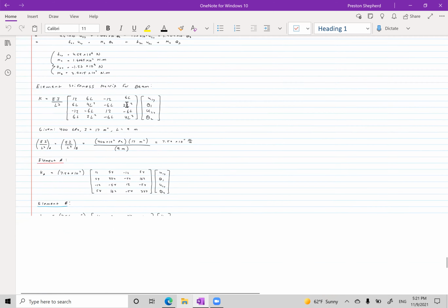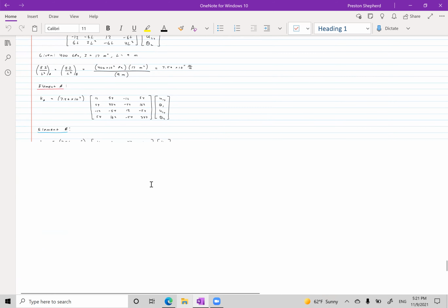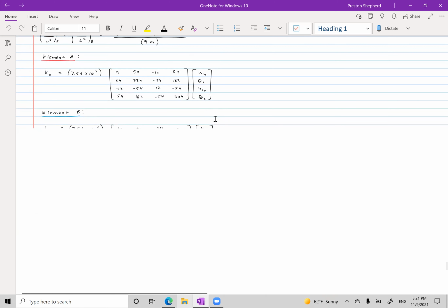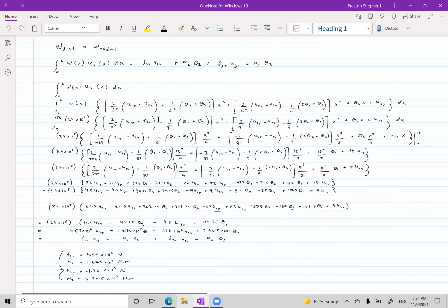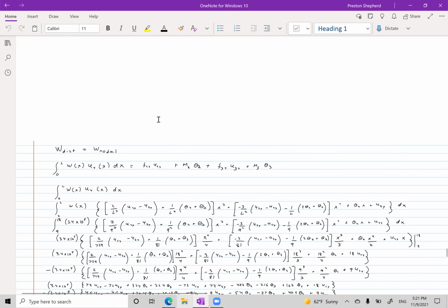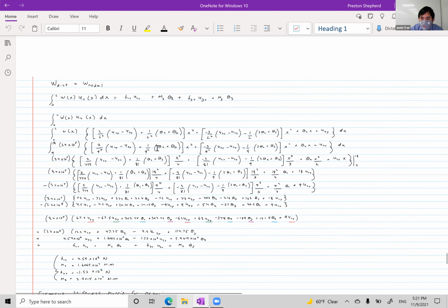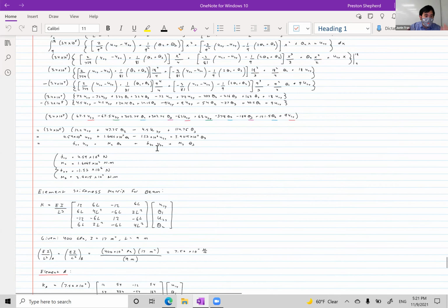And then I set up the global matrix, and basically it would just have the fixed constraint at the wall, correct? Yep. Taking a look at your nodal forces, maybe this is a function of you doing it from 9 to 18, but both of your f's should be the same, so both your f2y and f3y, because it's a uniform load.